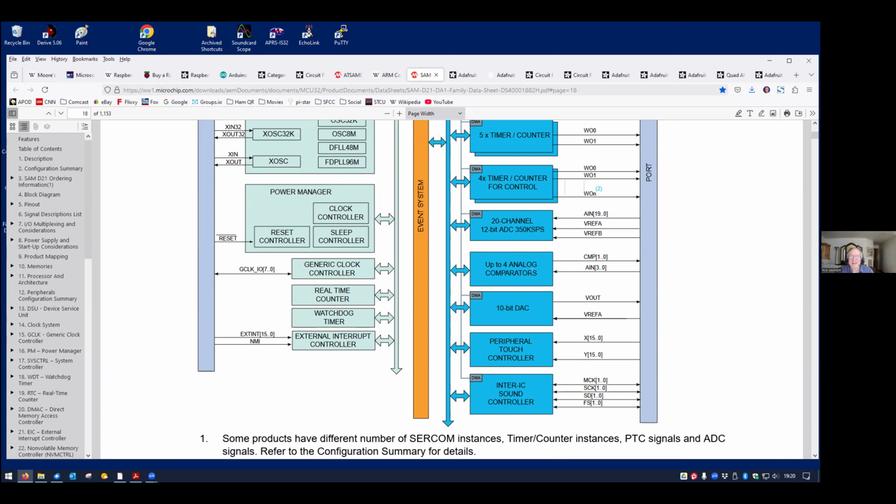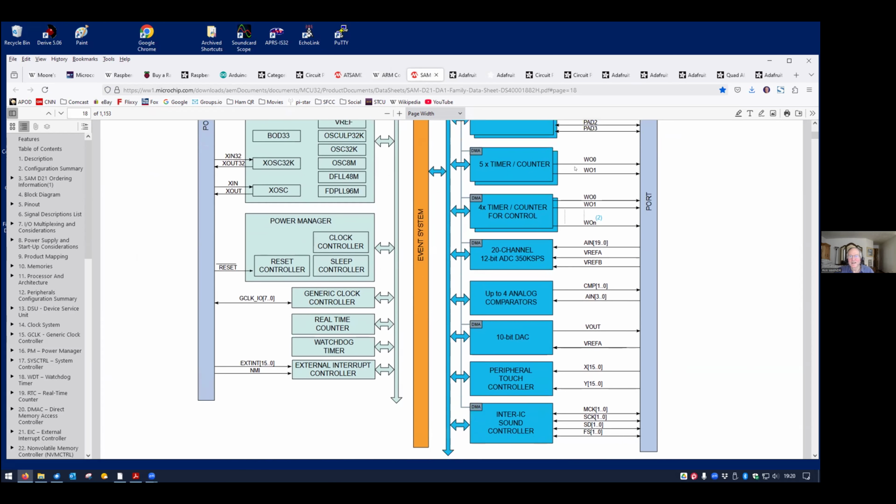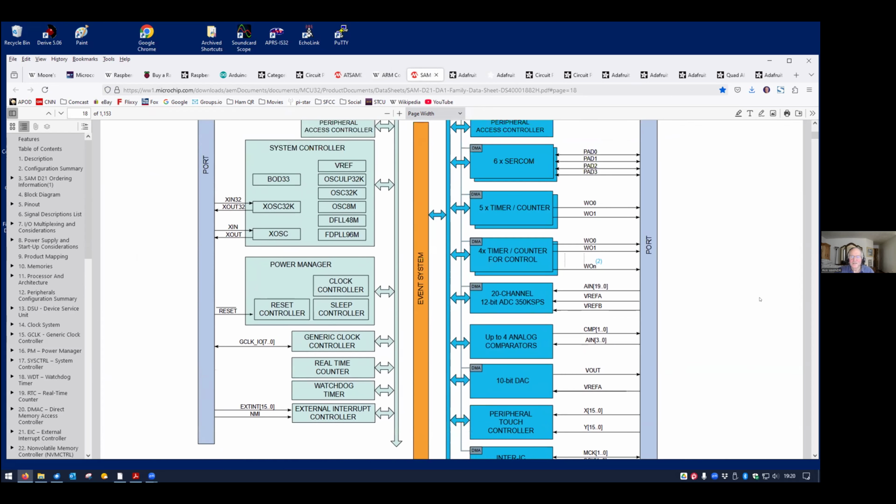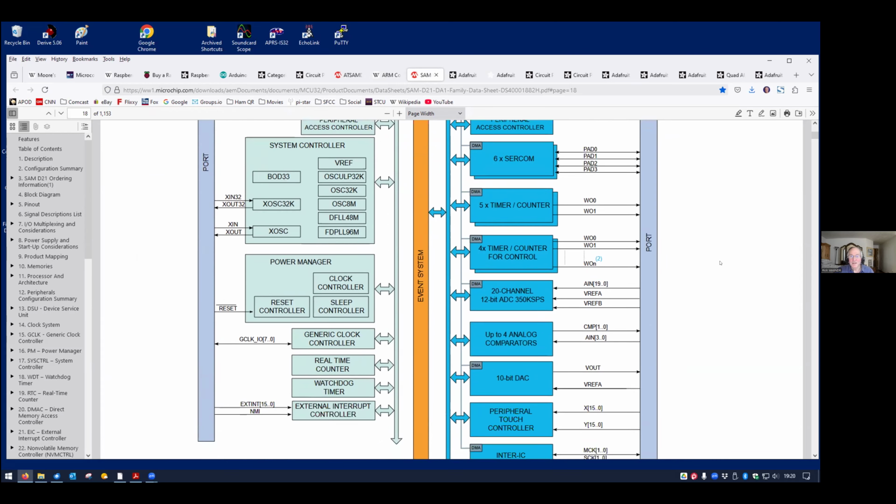It's amazing. Analog comparators, so this is for measuring analog things. 10-bit digital to analog. So this will take 10 bits and generate an analog waveform from them. Again, this is where you get things like audio, sine waves, square waves, triangle waves, things like that. And the various bus controllers. This thing with these various devices can do SPI, I2C, and USB, by the way.